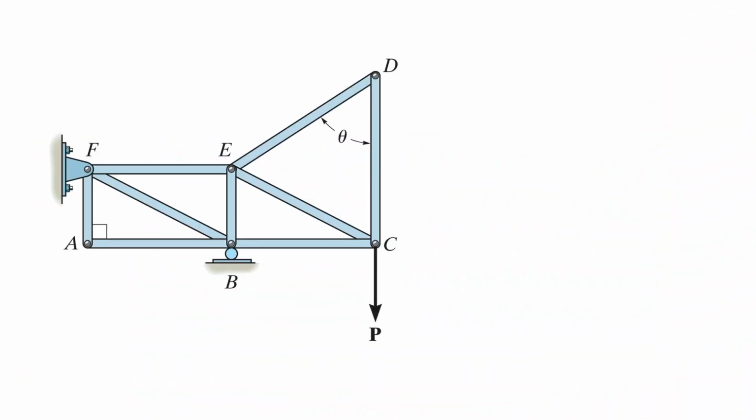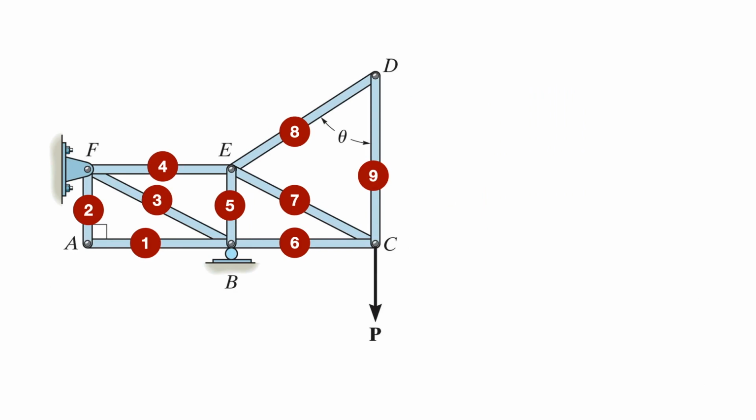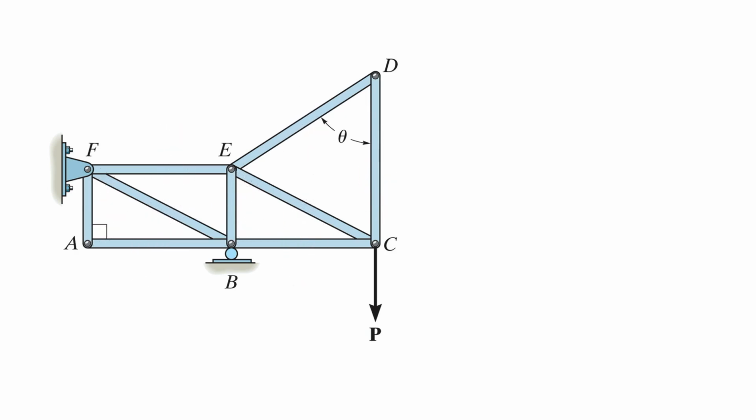Okay, look at this truss structure. It consists of 9 slender members. You imagine, before this, when working with only 5 members, the solution process can be quite long, right? So even more so when it involves 9 slender members. So, one way to simplify the analysis process is by identifying the zero force members. In order to find a zero force member, you start at a joint where there is no external force or no support reactions, a very free kind of joint.